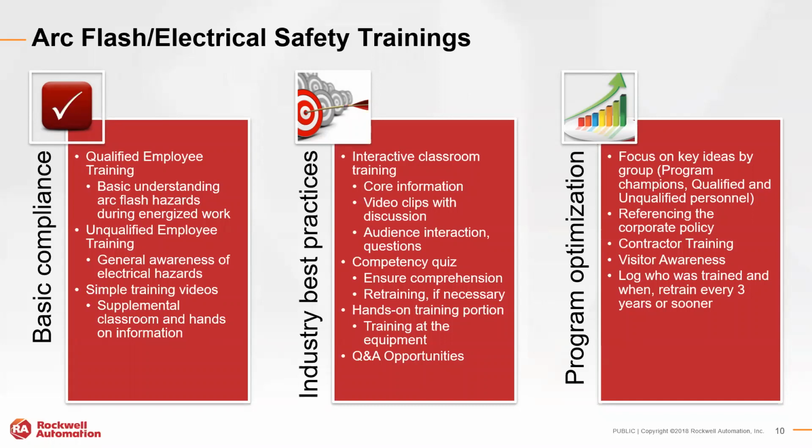Maybe that hands-on component also includes pulling up an arc flash label from an actual panel or piece of equipment out on the floor, going through specifically the considerations to take on that specific piece of equipment. So it's a good hands-on example. Going through the work permit process, maybe performing an actual task at that equipment with the PPE suited up to get some experience there, rather than just the training being totally theoretical in nature.